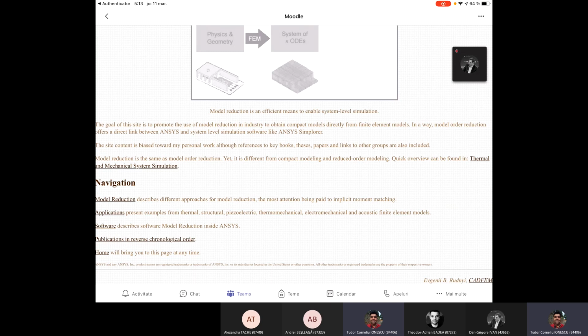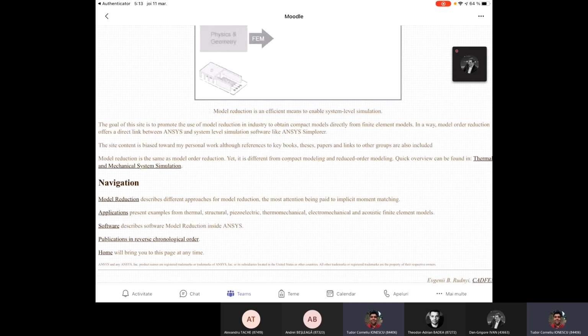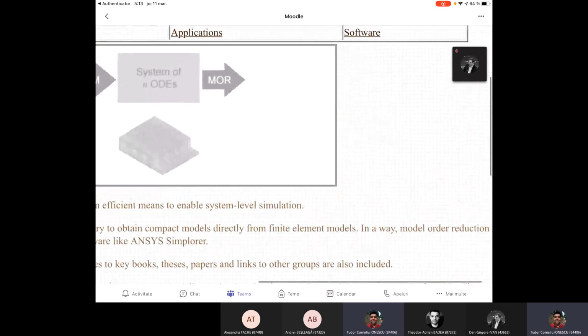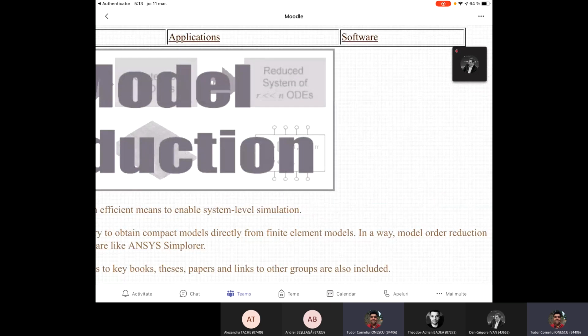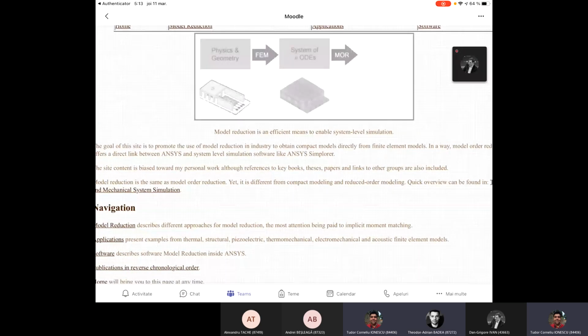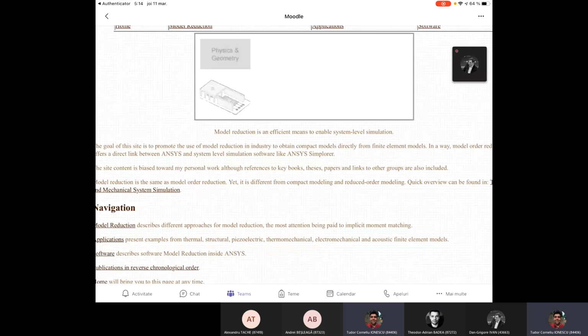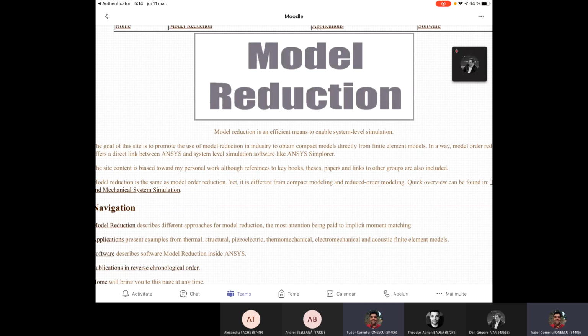What do they actually do? They discretize the space into grids, just like the little squares that you see here. Okay, just like this grid that you see on this screen. Yeah, a mesh, exactly, mesh or grid. So you discretize the space, and in each point of the grid or the mesh, you write a set of differential equations.